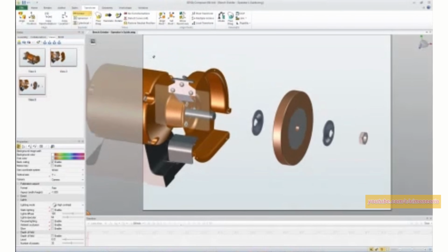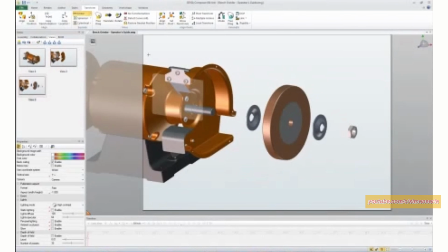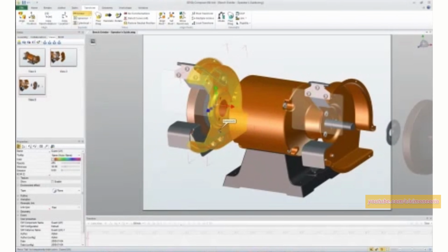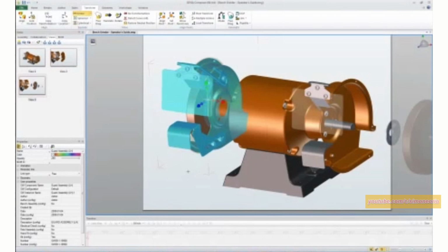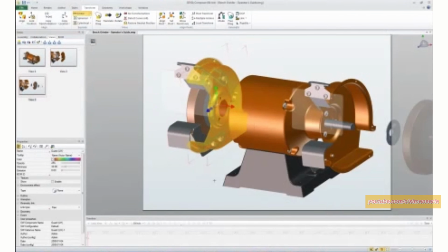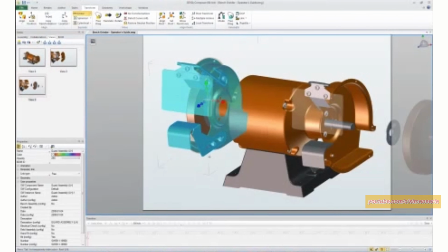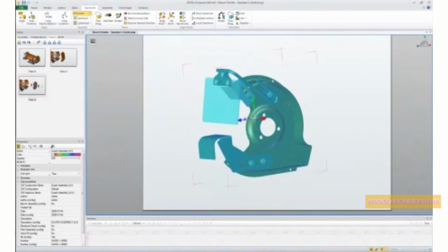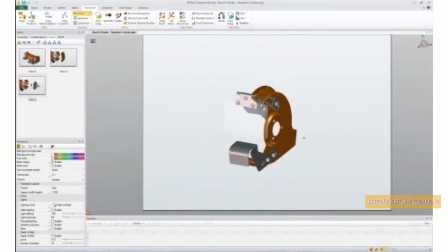And what I want to do is drag this over here, and I want to grab just this group of guys, the subassembly. So 3D Via Composer gives you some quick and simple ways, using arrow keys, for example, to select a particular actor, and using the arrow keys you can actually step up the ladder to select the entire subassembly. And then if we just want to hide it, we can hide everything that's not part of this subassembly very quickly again. And let's go ahead and add some more explode steps to this guy.